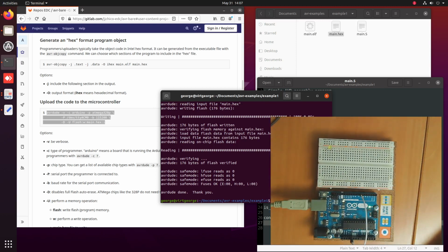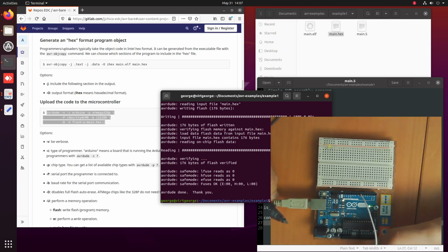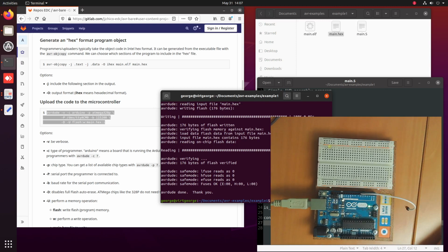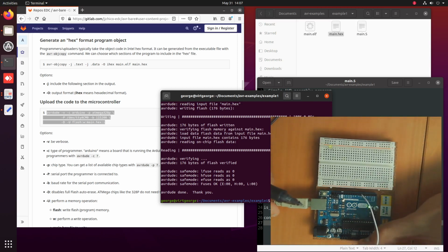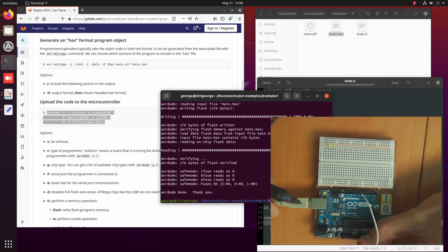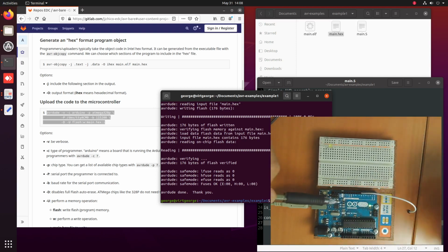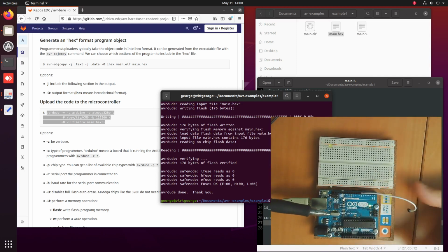Okay, what happens if I do not connect the cable? If you don't connect the cable, it's not a good idea, because who knows what it is reading. It may read a 0, it may read a 1. If I connect it to 0 and then disconnect, even if I touch the cable, the value may change.